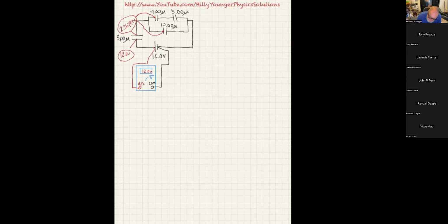If you were to draw a bubble from there, you'd say that's 0 volts, because clearly they're at the same potential. Because remember, I was leaving the black line connected there all the time. So if I put the black line and the red line on the same spot, you should get a voltage difference of 0.